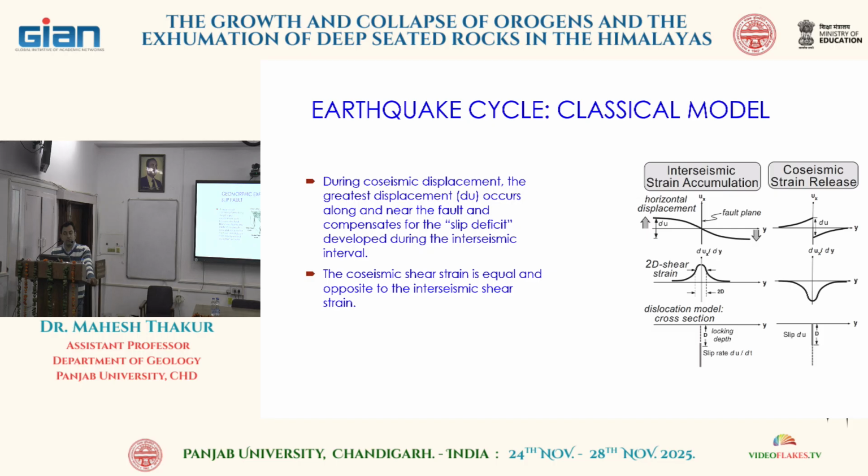In the afternoon, we will show you some Cartosat images in which you can see the ground in 3D, and you can have a sense that one block is uplifted and the other is down. Then you can trace out that fault along its length. Once you are convinced that there are many geomorphic markers present along the trace of this fault, then you can decide to go for fieldwork, and you should know beforehand which kind of features you want to observe in the field. It's not like you just go and search, because you want to optimize your time in the field.